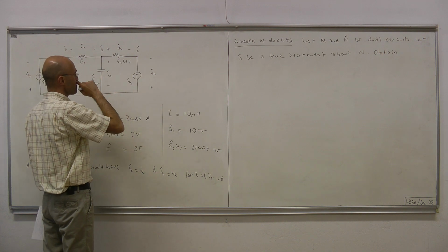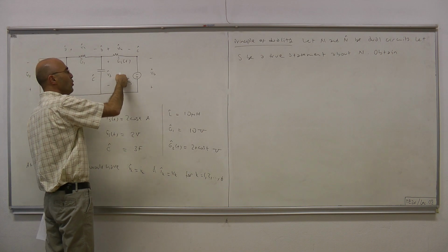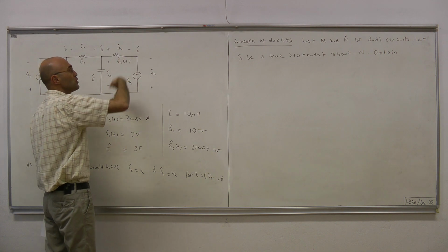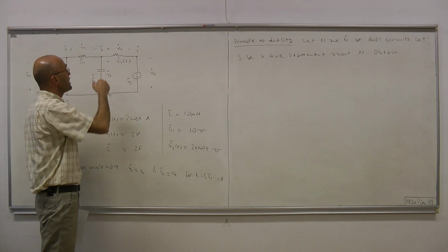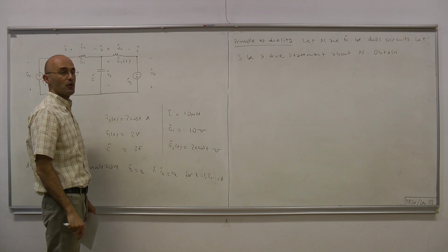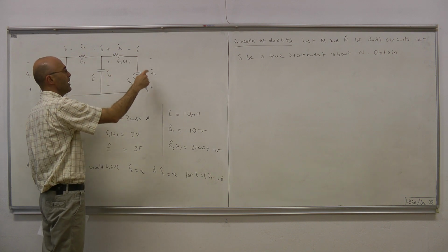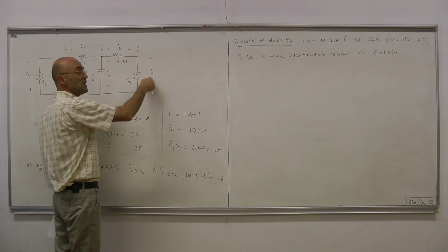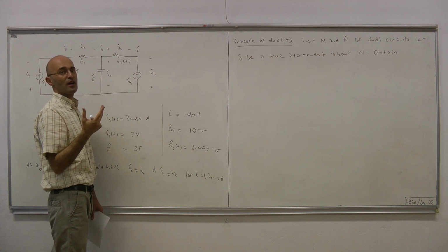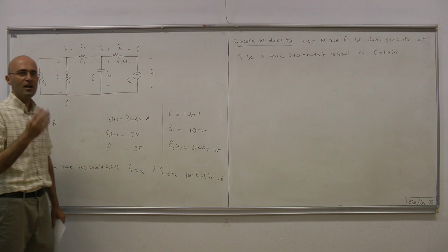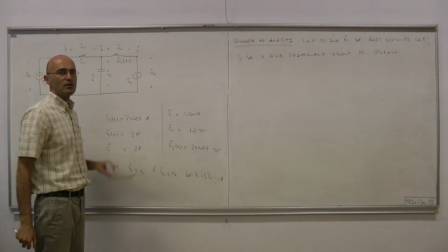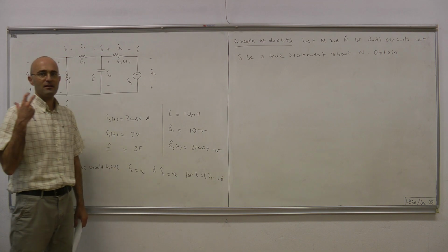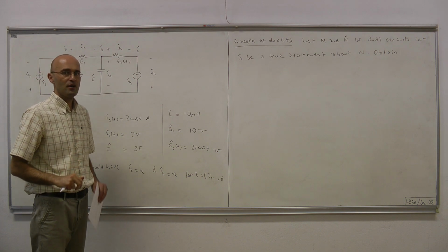For the dual circuit, if this is mesh M3, let's say, for the node M3 hat, there are 3 currents that are either entering or leaving that node. And those currents are I3, I4, and I6. And among all those currents, the one with the largest magnitude is I6, and it's 12 amps. Okay, so what you do is, when dualizing a statement, you swap all the terms with its dual, and what happens is that the dualized statement is also a true statement.